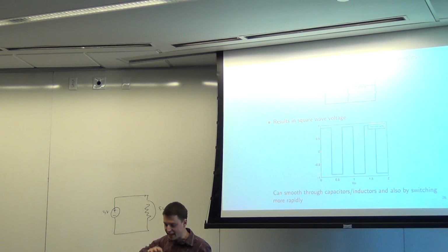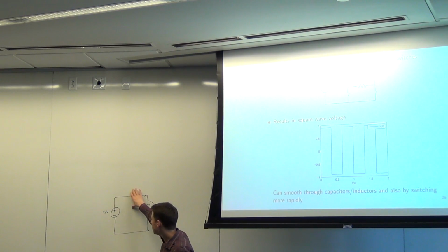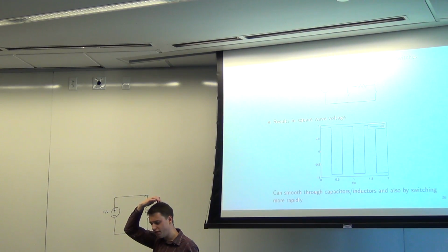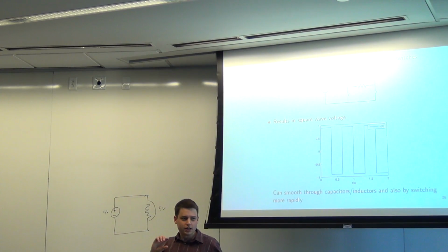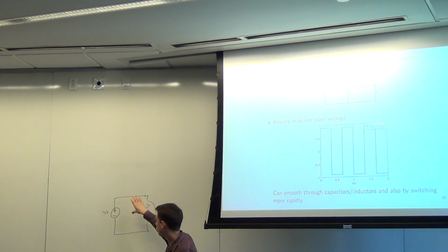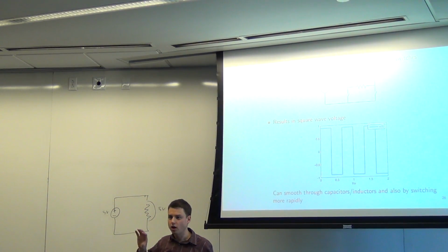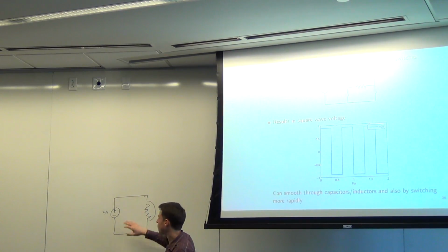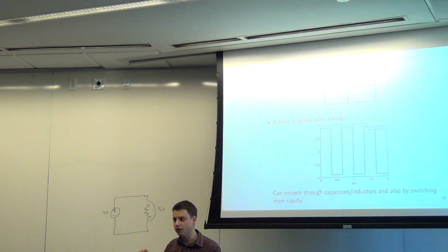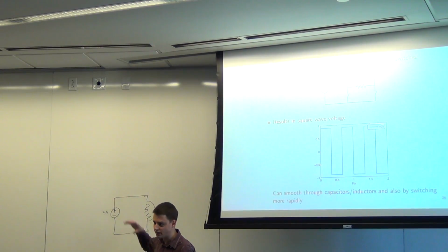So it's pretty easy to step down DC voltage, but this is very wasteful. A lot of DC voltage controllers that you will see, though they aren't quite this bad, work similarly. Linear voltage regulators, for example, if you've heard that term before, that's great; if not, don't worry about it. They don't do exactly this, but what they do still effectively burns up some amount of power and dissipates it as heat in order to control the voltage at the end.